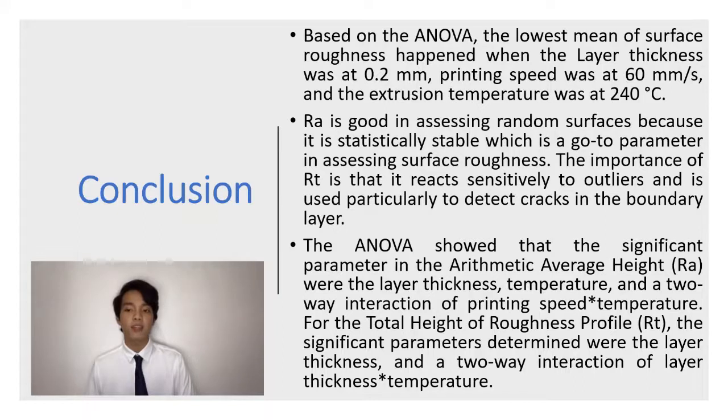Layer thickness of the specimen was optimum at 0.2 mm. This supports that having a lower optimum layer thickness provided a reduced number of voids which were deposited during the extrusion of the filament. Printing on higher layer thickness gave a higher surface roughness value because the layers don't stick properly because of the voids present during the extrusion, which results in poor surface finish.